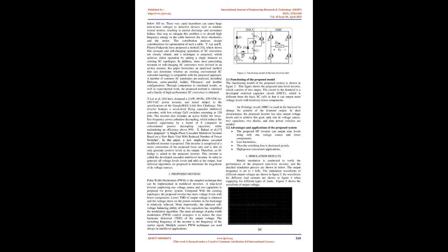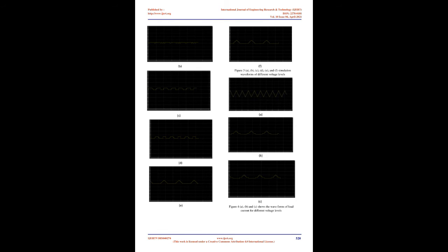A non-isolated multilevel step-up DC-DC converter suitable for high power and high output voltage application is proposed by L.F. Costa et al. The main features of the proposed converter are reduced voltage across the semiconductors, low switching losses and reduced volume of input inductor. This paper focuses on the 5-level structure of the proposed converter, in which the theoretical analysis is carried out and discussed. The 5-level proposed DC-DC converter has 4 capacitors and their voltages should be balanced for its correct operation.